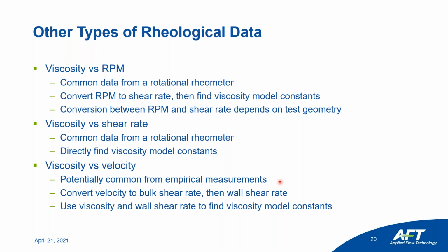And once we have that wall shear rate, we can use our viscosity and that wall shear rate to find our viscosity model constants. So again, these are just three potentially common types of rheological data. Goodness knows there's an endless number of forms you might have data in.